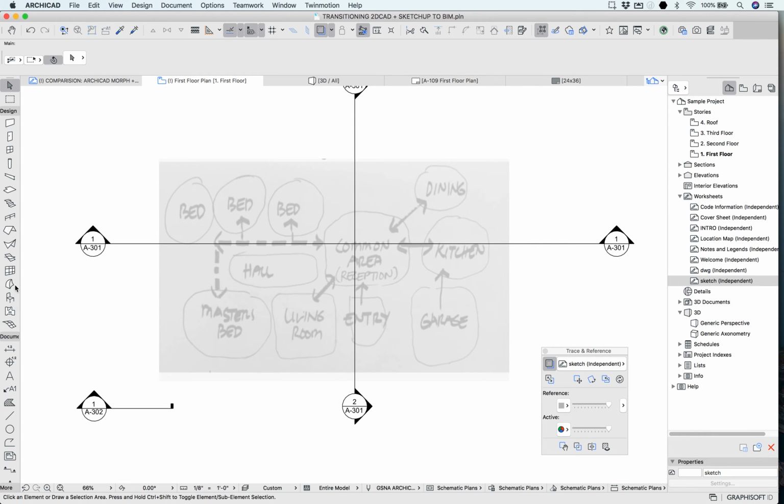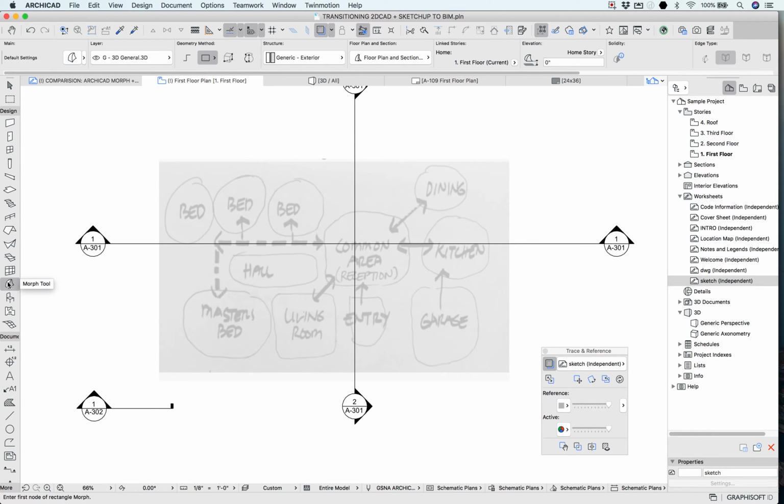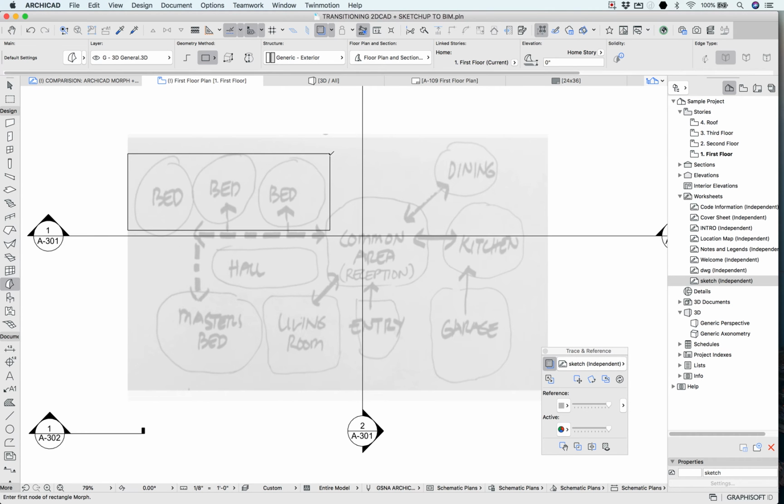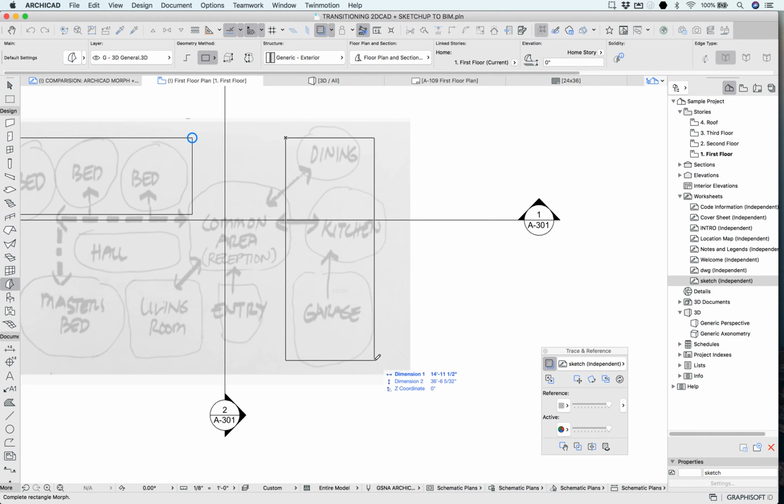So what that looks like from a model building perspective, we have our morph tool. We have these different methods. I'm right now just going to build a face. But let's say I want to represent this mass here, and I just built that one. But if it was about me defining actual dimensions, you can use special guidelines to help me do that. And if I wanted to be more specific, for instance, make this mass 15 feet by 38 feet, I'm going to enter that information here.